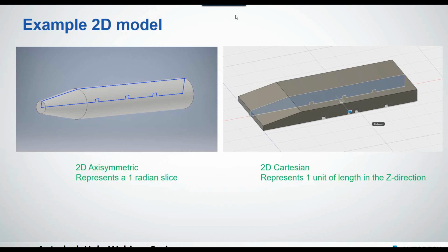So I'm just going to touch on that again, just because people do get tripped up and ask questions here. A lot of times when you set units in CFD, I don't really care if it's millimeters or centimeters. I'm kind of going on the fly, and it's all in my head. But this is a place where it really matters, because I've seen people use several millimeters per second of the volume flow rate and have their base units in meters, and they don't have any flow, and they think something bad is going on. So when you have units that are 3D, you really just have to be smart about how you're analyzing it. And a great thing about 2D is pressures and velocities are kind of the same, because those aren't 3D quantities. But yeah, super important for 2D.